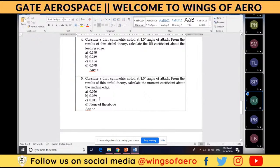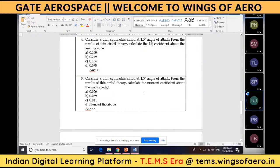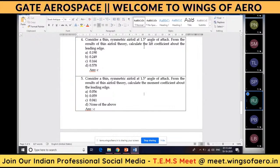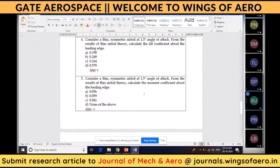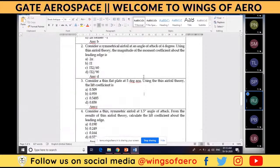The answer is 0.041. Here, the same way, first we need to change the angle of attack from degrees to radians. After that, apply the lift coefficient 2 pi alpha. So alpha is 1.5 into pi by 180. By applying that, we will get the answer. Here also the same only.